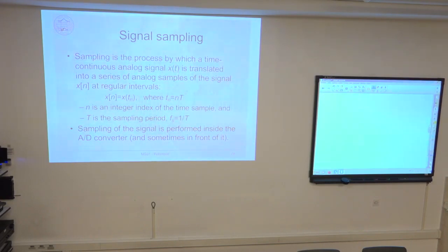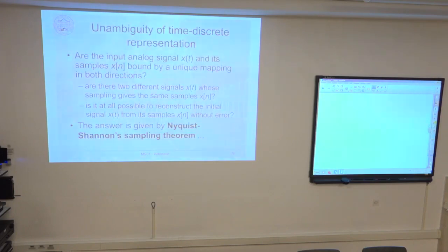It will take the sample, keep this continuous value until the AD converter converts this value to digital form, and then take another sample, again keep this analog value for a given time until the conversion is done. This sample and hold device can be integrated into the AD converter, or it can be implemented as a separate component in front of it.